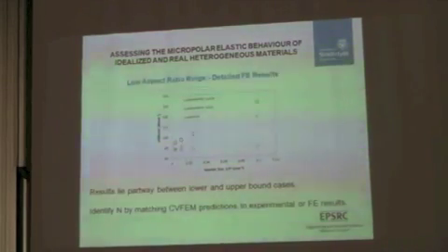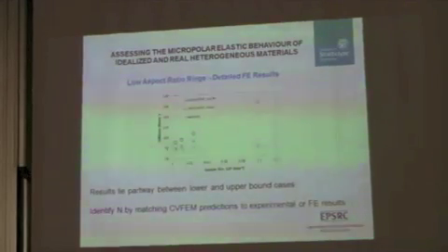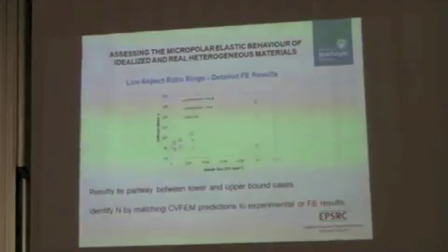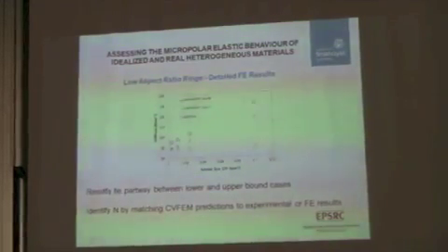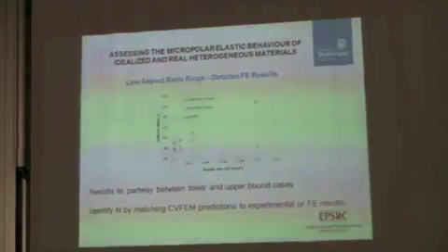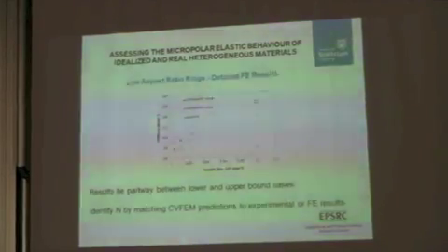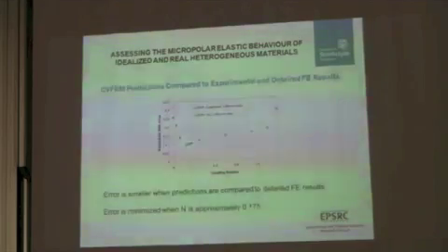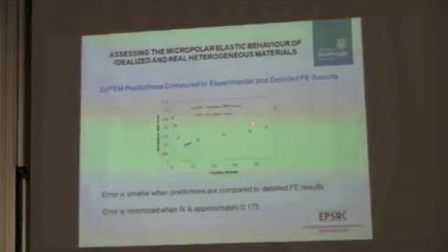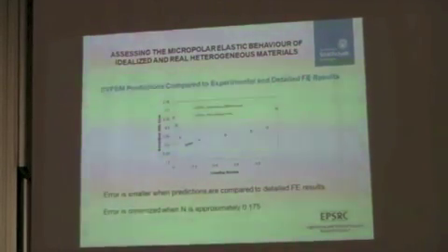Having got that data, I can try to identify the appropriate value of the coupling number by matching the numerical predictions from our own in-house code, containing the micropolar elastic behaviour, to this measured data. That's what I do in this graph, where I'm measuring the error between our predictions and our measured data against coupling number. Each data point is the cumulative error for all 4 samples that we're testing.